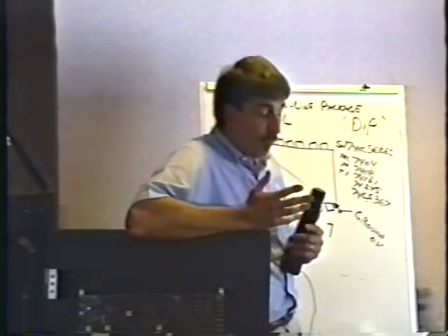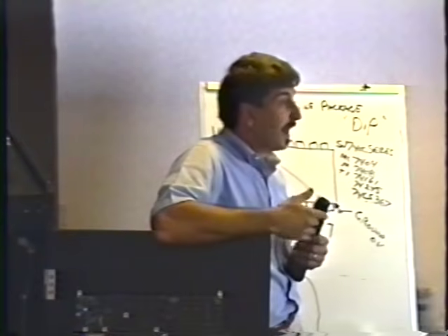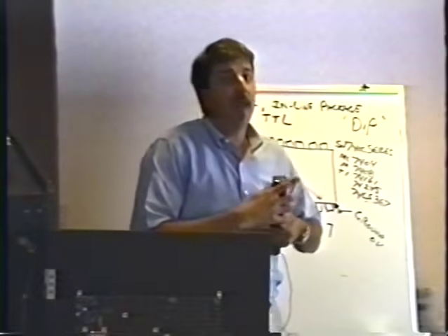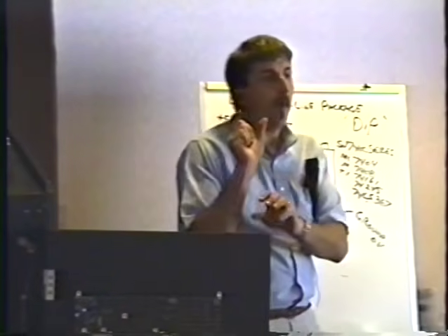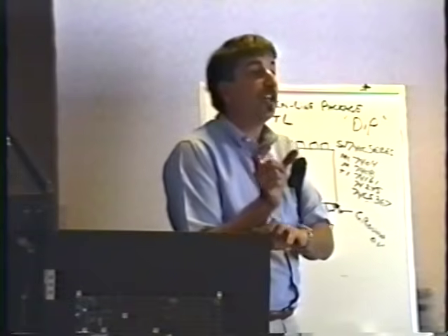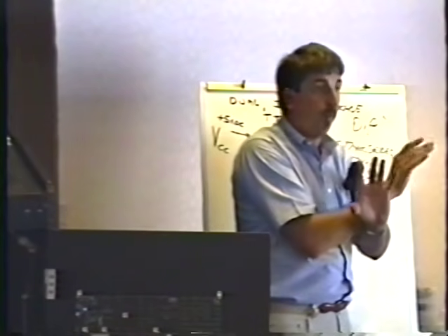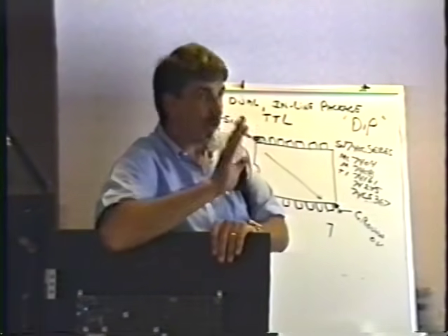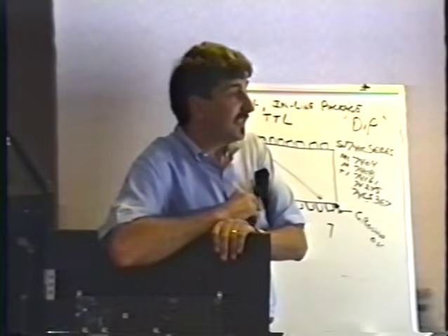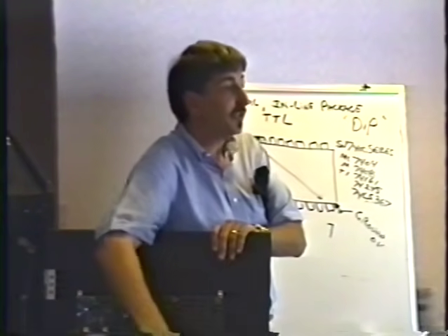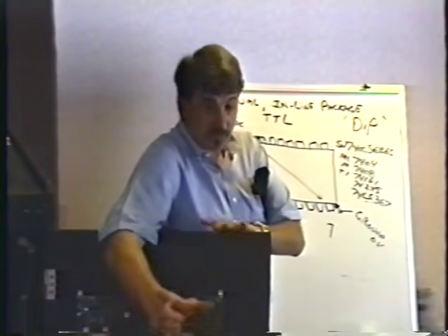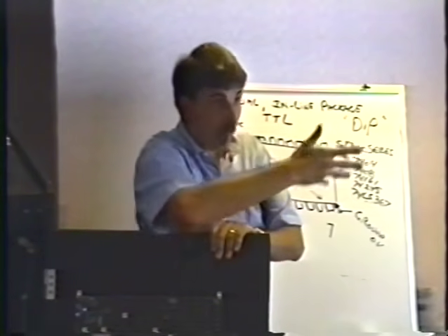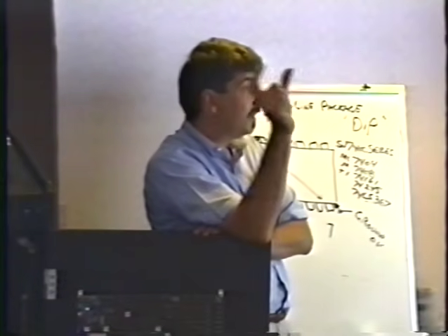So I took the bad boards and I drove 20 miles over to a location where we had another Outrun, and I sat down behind the Outrun, and one at a time I took the integrated circuits from the bad board and swapped them with the good working board. You should always do this. Try the suspected bad parts in your good working test bed. The reason you do this is that you may have more than one bad integrated circuit on your bad board. This way, when you move a chip over, you can tell, oh, I moved this chip over, now the problem's in my working game. Obviously, that chip that I moved over is bad.